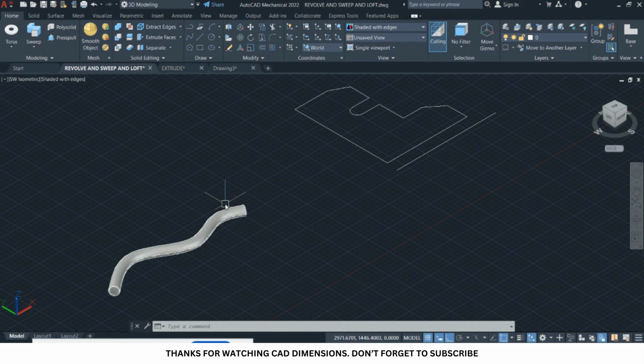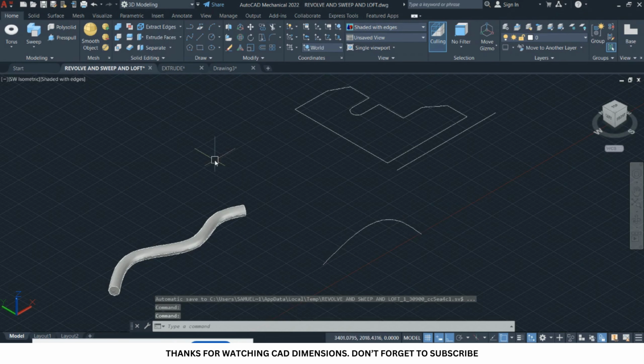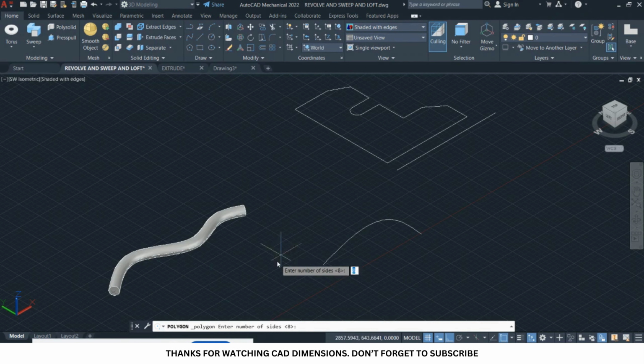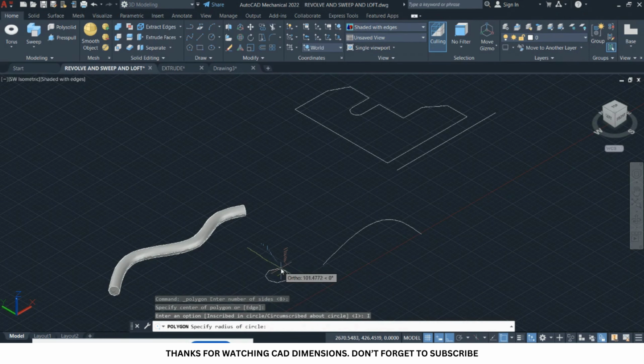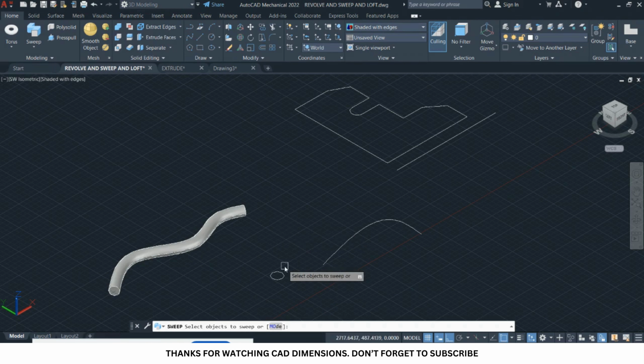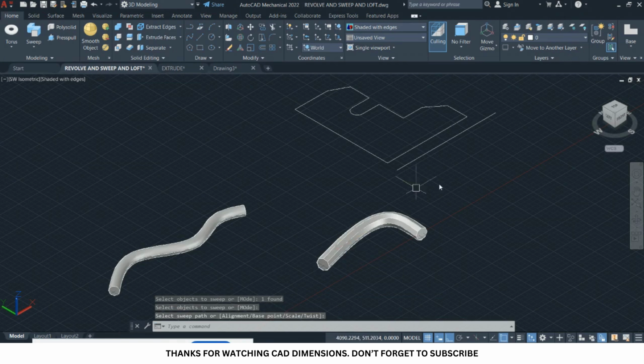So you can play around with it, get your own shape somewhere that you want to try your hands on. So maybe this shape. And maybe you want to draw something like this, something small, then you create your sweep. So select the sweep, select this, you press enter, then you select this, then you create the sweep.